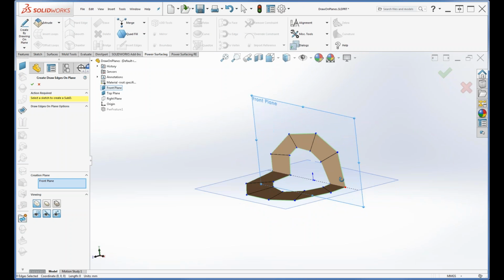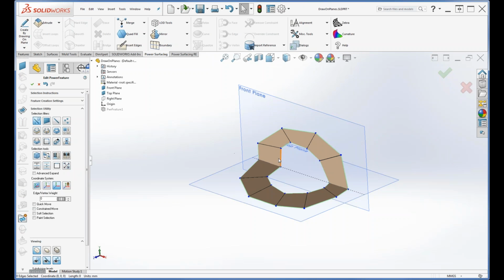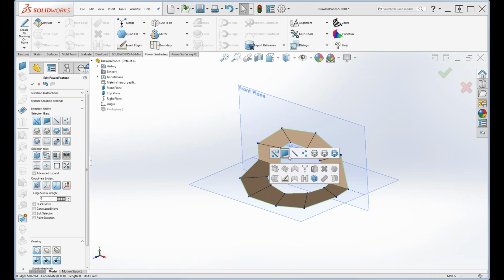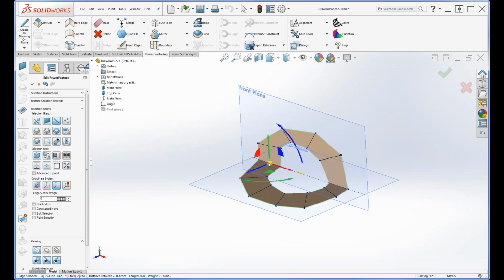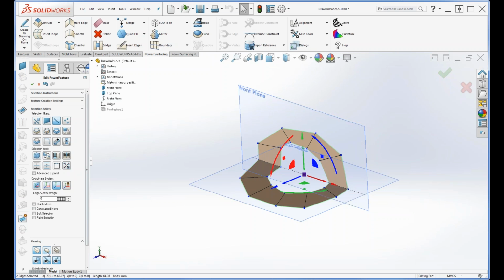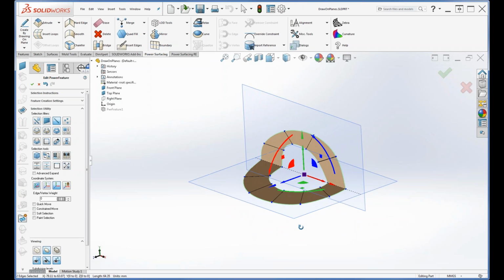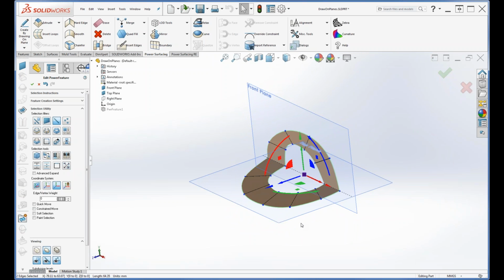And there we go. Right now you're seeing the control mesh, so I'll right click to finish this. If you wanted to retain these creases, you probably want to select these two edges and set them to 100% weighted. Then if we look at it in sub-D mode, that's what we've got. From there you could do whatever you want with it. You could extrude it, thicken it, you could do all sorts of things.